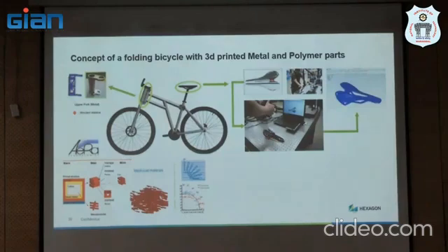Now I scan the material. I know the loading condition. So it will tell what is the required property. Now you can develop your own material. Use it to print a coupon. This is pretty much possible in composites, because when you have a different carbon fiber orientation, you will have a different strength in that particular direction.